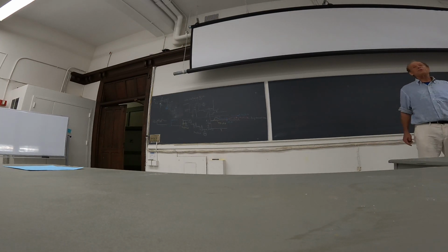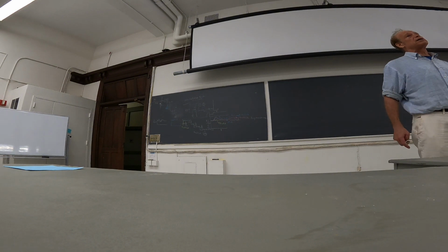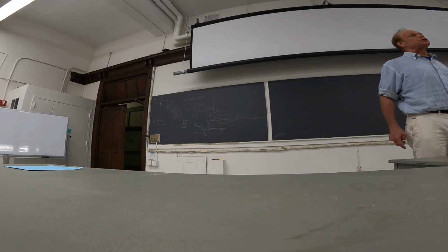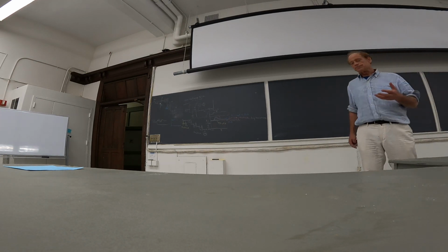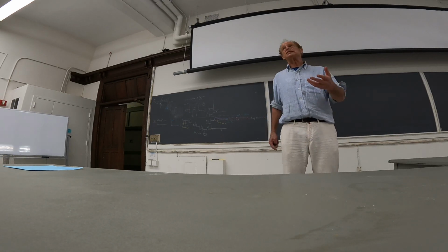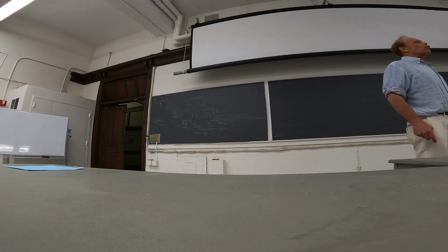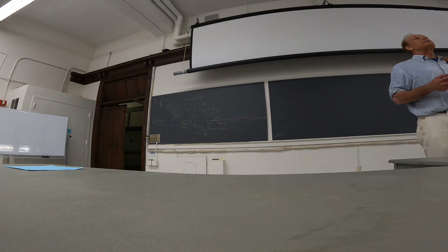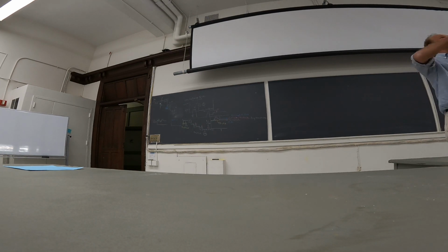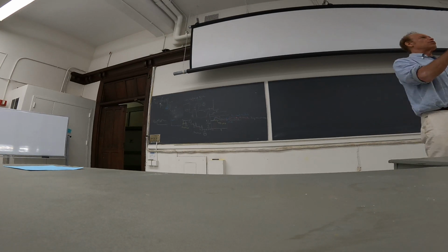So, the fluid mechanics of that is quite complicated. You can try to simulate it, but at the end of the day, what they actually do is they would like to have a physical model much smaller than the actual ship and actually measure the resistance in the water. And in order to do that, to have an experimental model, you have to make sure that you have dynamic similarity. Dynamic similarity means you write down the overall governing equations, even if you can't solve them. You non-dimensionalize them, and you make sure that the non-dimensional groups, like the Reynolds number, the Froude number, etc., the physical ratios, are the same in the model system as they are in the big system.